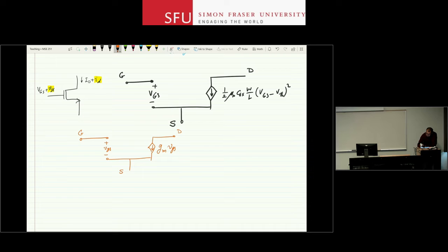So remember what we had for gm for BJT was the changes of IC due to the changes of VBE, right? The slope of that curve for a BJT. MOSFET is the same. So if you go and calculate delta ID in response to VGS, you can estimate that gm for a MOSFET, right?